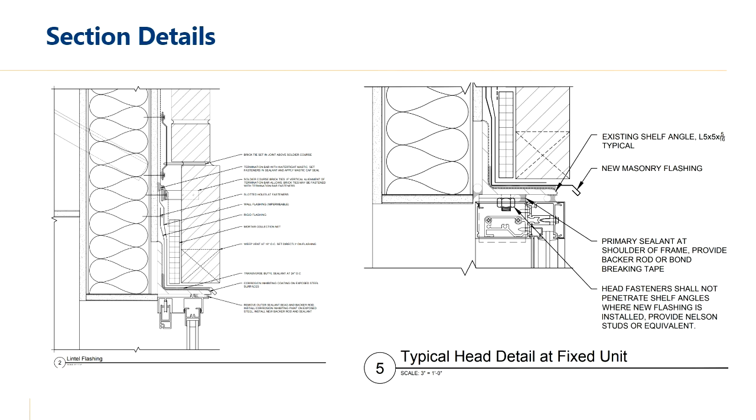Here's an image of what your typical section details might look like. These can help you solve a lot of problems. You can cover the types of materials. On the image on the left, you can see we're paying attention to how anchors are going to be aligned with our flashing. We want to make sure that nothing is penetrating our flashing that goes through the back of it.